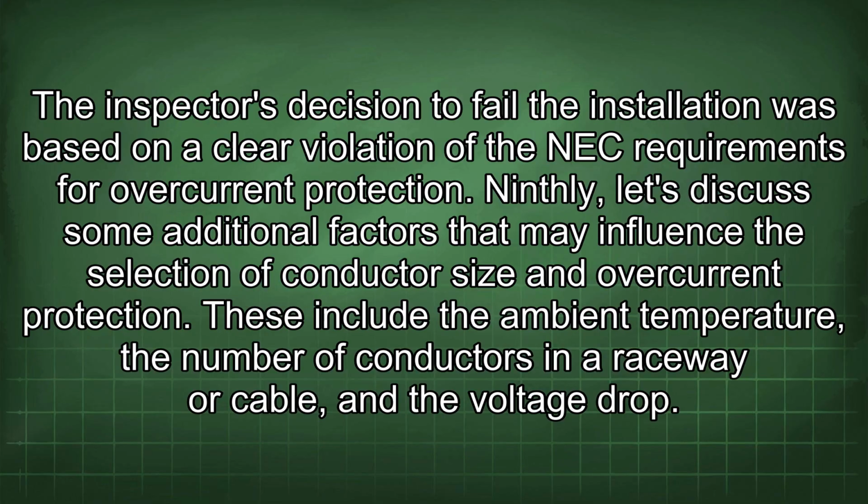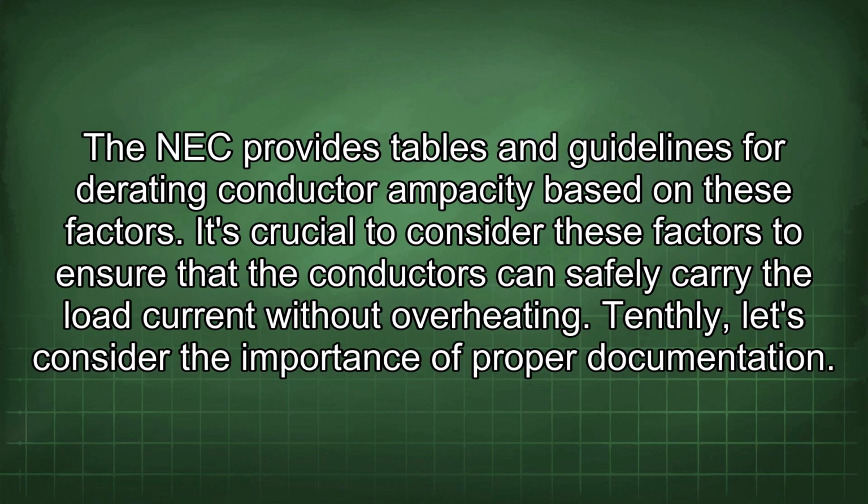Ninthly, let's discuss some additional factors that may influence the selection of conductor size and overcurrent protection. These include the ambient temperature, the number of conductors in a raceway or cable, and the voltage drop. The NEC provides tables and guidelines for determining conductor ampacity based on these factors. It's crucial to consider these factors to ensure that the conductors can safely carry the load current without overheating.